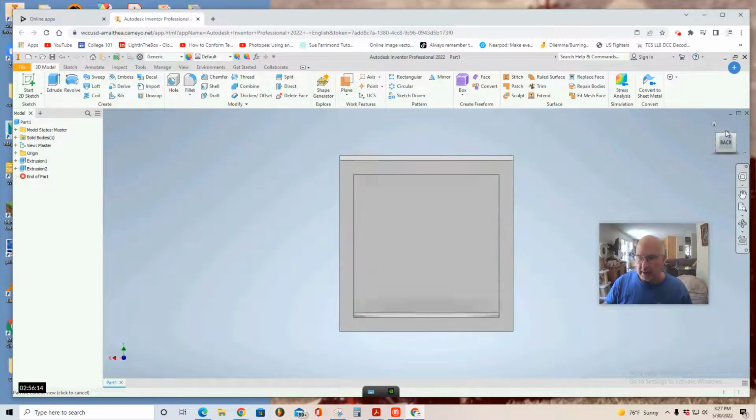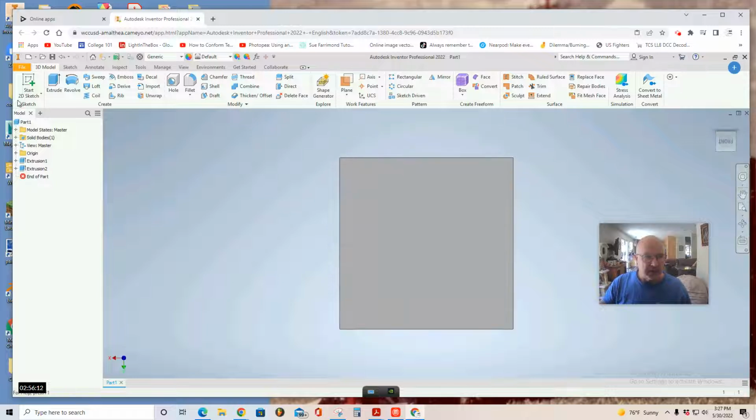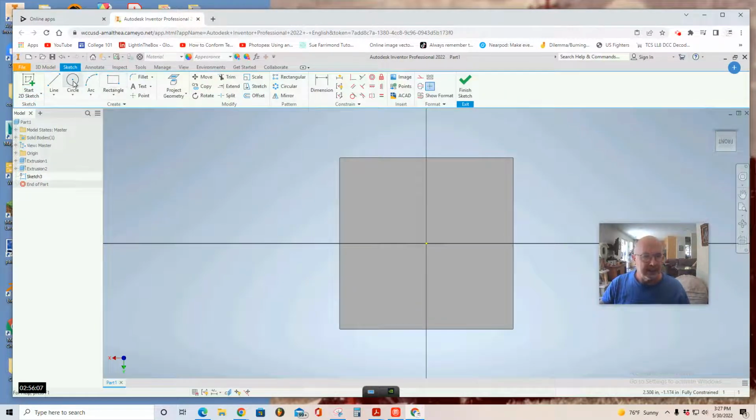Now I'm going to rotate to the top and start a 2D sketch on the top of my Duplo to make the 4 pins. You'll start with a circle, click, and I measured the thing with a micrometer, and it was 0.374. Your diameter, and now I'm going to select a second circle on the ID, interior dimension, and just put a 0.3 for the diameter for that circle.